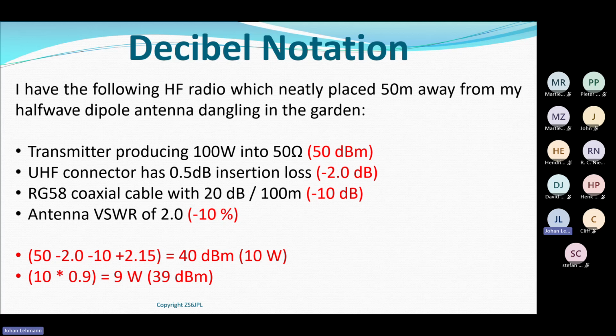There's a rule of thumb I always tell the new people: whatever you spend on the radio, you must be prepared to spend on the balance of the system. In other words, connectors, cables, antennas, everything that goes with the radio. Otherwise, you are, in some sense, wasting money. If you look at this example, 100 watts becomes 9 watts. Are there questions on this one before I move on to the next scenario?